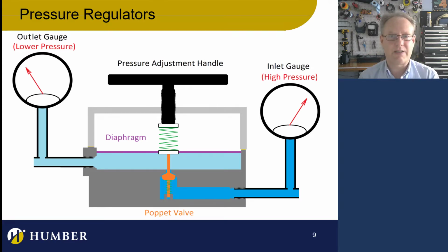So what's happening is that I have pressurized air going into my system over here. It's high pressurized air going into the system, and it goes up into here, and there's this little thing called a poppet valve. Now, there's a spring here and a diaphragm, and let's get into the mechanism. Imagine the air going downstream, the air going out. Now that's going to a pneumatic actuator. It could be going to just an air gun, right? Or someplace, whatever it is.